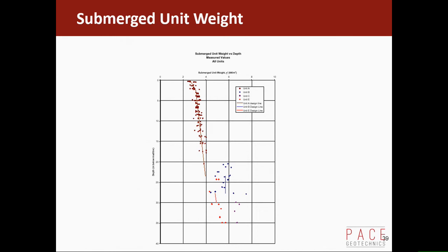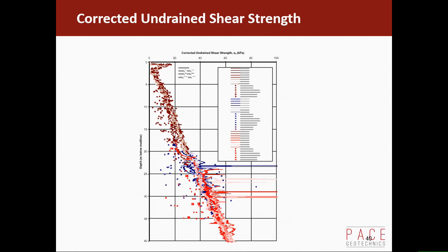Submerged unit weight increases slightly with depth because the weight of overlying soil has squeezed more water out as you go deeper. And then we came up with some design lines. Can you see that? Yeah, the design lines just in there.